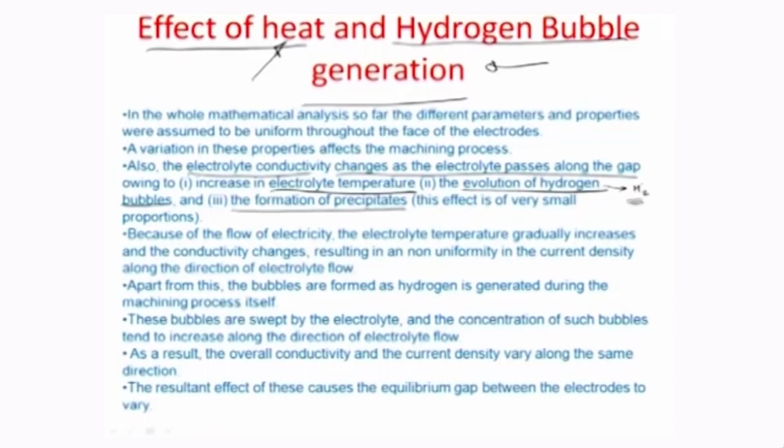This would have its own connotations because it would impose a change in local conductivity because of circulation of this small debris, called precipitate, which is coming out into the ECM electrolyte. Although that precipitate effect is very small in terms of change of overall electrolyte, you do have to consider it, and particularly for microsystem design or microsystem fabrication, this may be a very important aspect: the changes of conductivity because of precipitates of all sorts of materials.